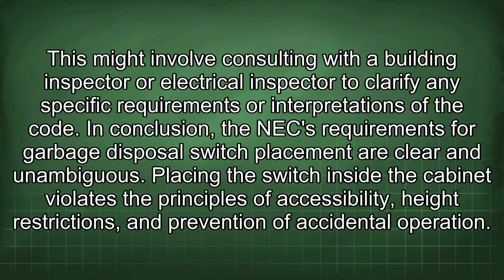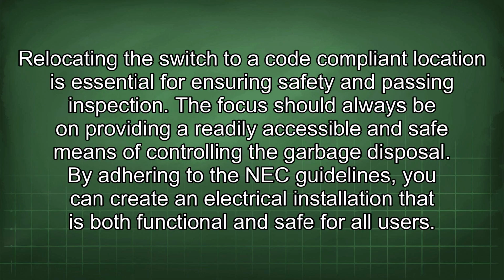In conclusion, the NEC requirements for garbage disposal switch placement are clear and unambiguous. Placing the switch inside the cabinet violates the principles of accessibility, height restrictions, and prevention of accidental operation. Relocating the switch to a code-compliant location is essential for ensuring safety and passing inspection. The focus should always be on providing a readily accessible and safe means of controlling the garbage disposal. By adhering to the NEC guidelines, you can create an electrical installation that is both functional and safe for all users.